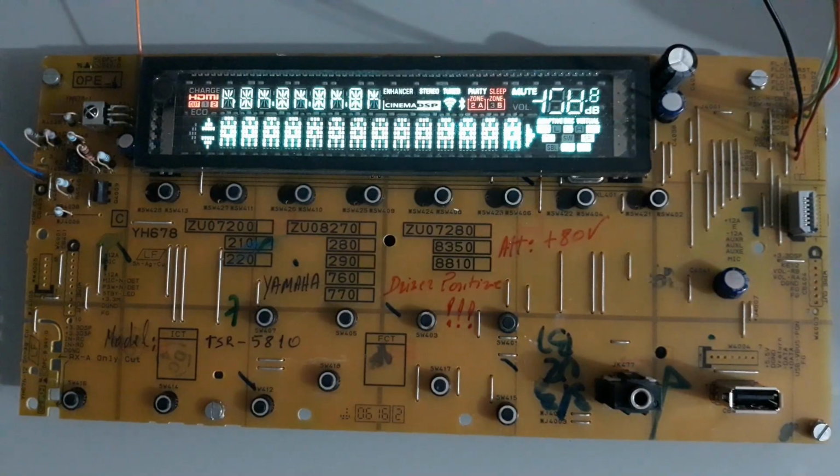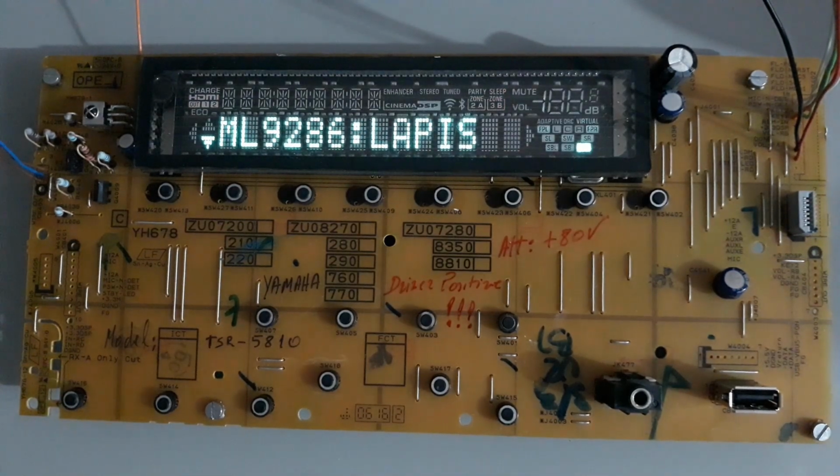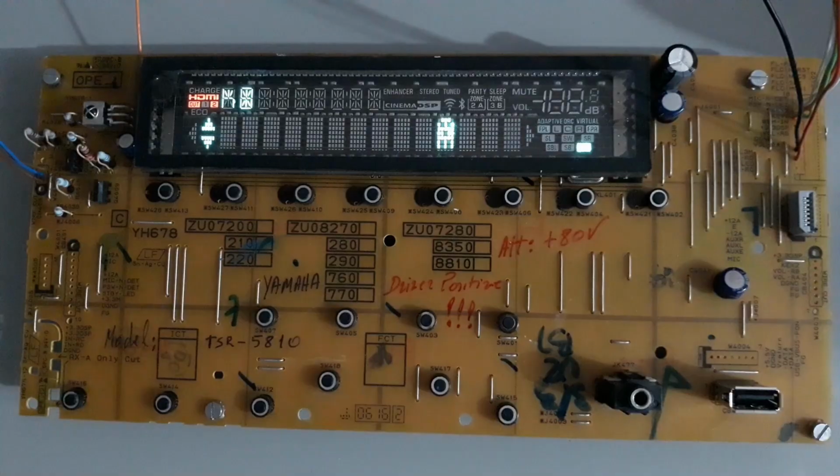So, for safety, we should not exceed the plus 39 volts DC for the VDISP. Also, it is necessary to check the voltage supported by the transistor which does the switching of this voltage.